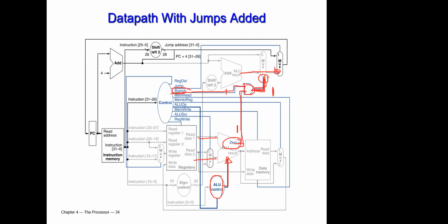This ALU control will have an input that's coming from the ALU op. And as we will describe later on, this ALU op will be extracted from my instruction. After that, it will go to the ALU control, and the ALU control will have a certain particular output according to certain particular codes, as we will see shortly.